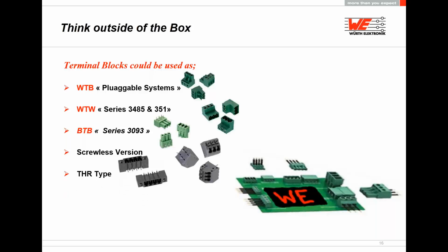Through hole reflow type, because a lot of people think terminal blocks are through hole, which is, yes, absolutely. We have one version that's a surface mount. But as long as it's a through hole, it would be better, since you can save time and money on the process by having it as a through hole reflow.